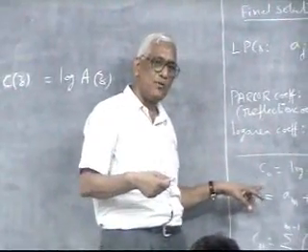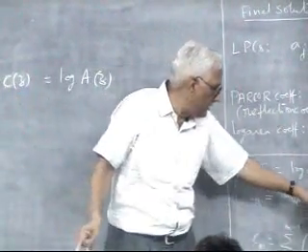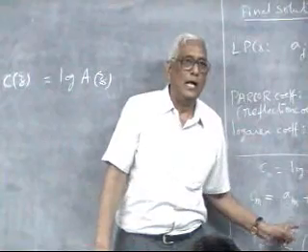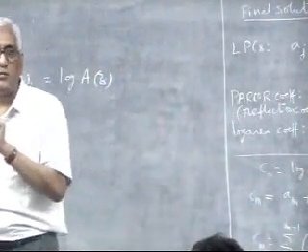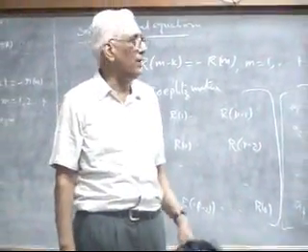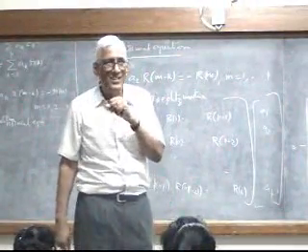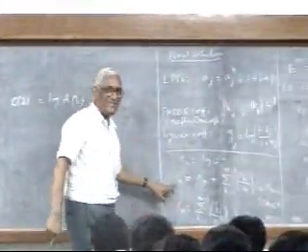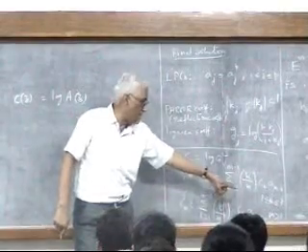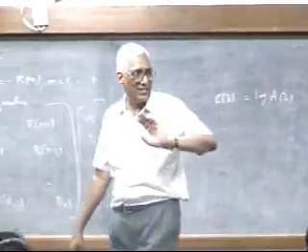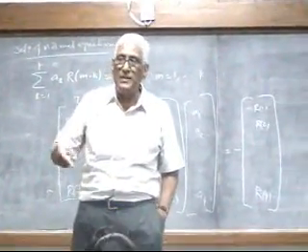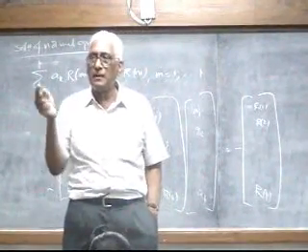And when you do that, the beauty of it is you will get these C's in terms of these A's in a recursive relation like this. And since there are only P coefficients in A, but unfortunately the C coefficients are infinite, up to P this is the equation, and beyond P, use this, that's why M greater than P. For M greater than P, you get this. So in fact, these are called the LP cepstral coefficients, linear prediction cepstral coefficients.